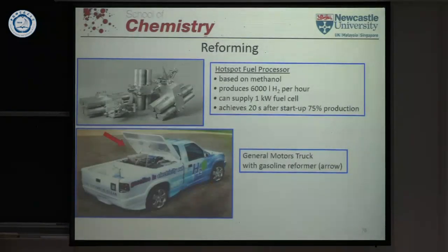Now there are sort of examples, and people about, let's say, 15, 20 years ago have thought a lot about using fuel cell cars and using a fuel that is not hydrogen, but is actually either an alcohol or is a hydrocarbon. And then you have to put actually all these processing units, the reformer and the shift converters and the cleaning into the car.